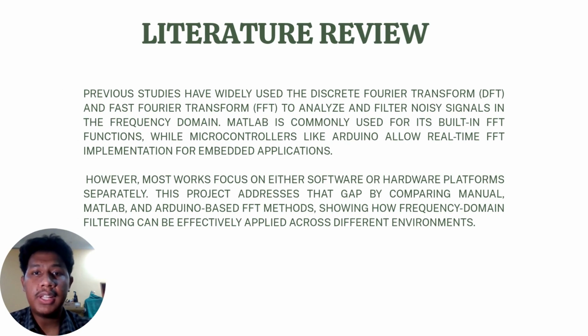Previous studies have widely used the discrete Fourier transform (DFT) and also FFT to analyze and filter noisy signals in the frequency domain. MATLAB is commonly used for its built-in FFT function, while microcontrollers like Arduino allow real-time FFT implementation for embedded applications. However, most work focuses on either software or hardware platforms separately. This project addresses that gap by comparing manual, MATLAB and Arduino-based FFT methods, showing how frequency domain filtering can be effectively applied across different environments.